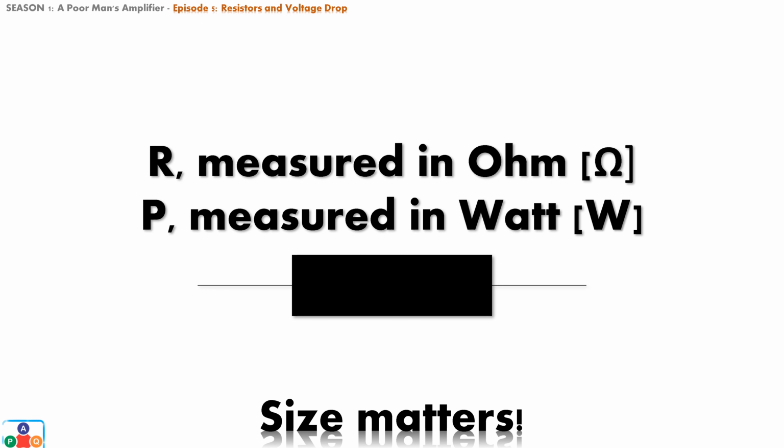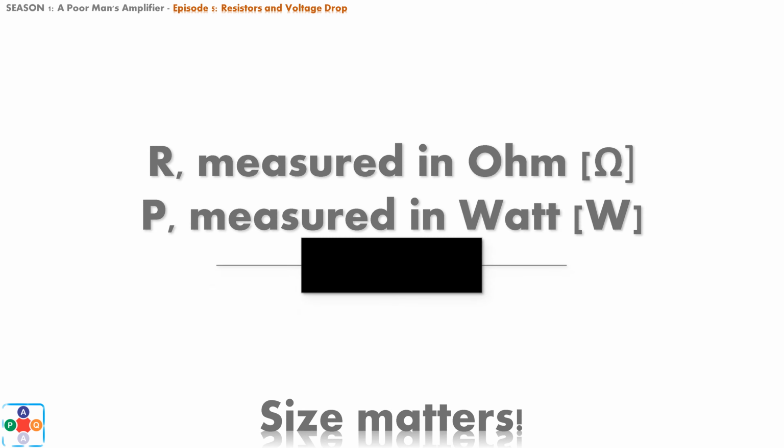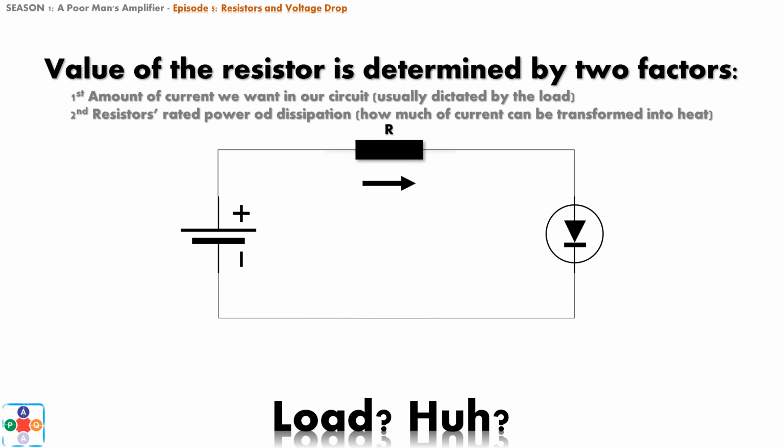Let's get back to our schematic, and this time, we will put the resistor between the battery and the LED diode. As previously shown, the problem with the original circuit, the one without a resistor, was that the flow of current in the circuit was unregulated, and as a result, our LED diode burned out. To mitigate this problem, we introduce a resistor in the circuit. As we have said, the purpose of a resistor is to regulate the intensity of the electric current in the circuit.